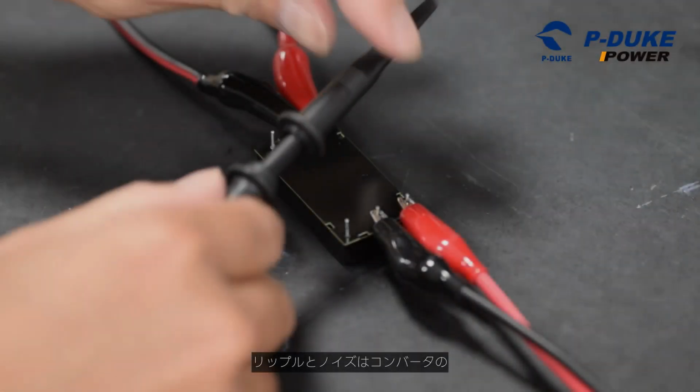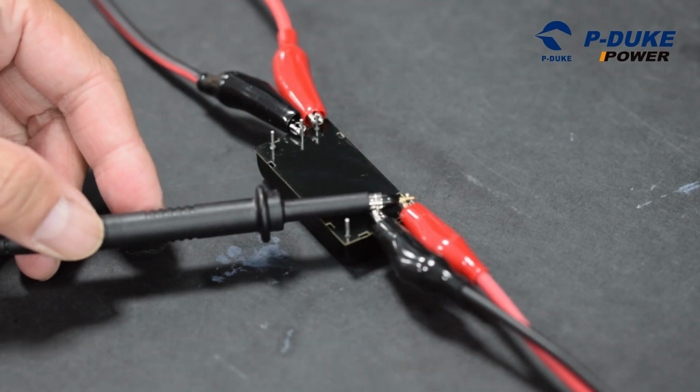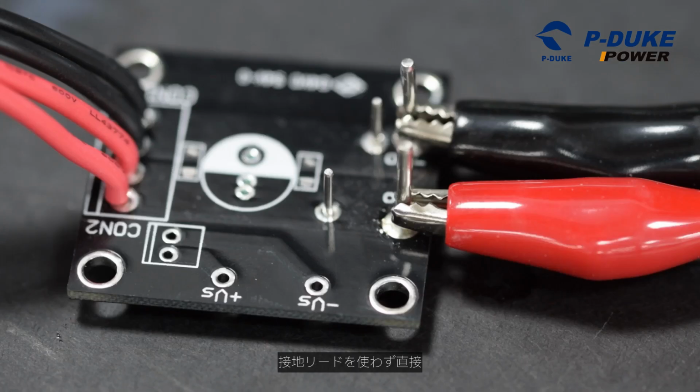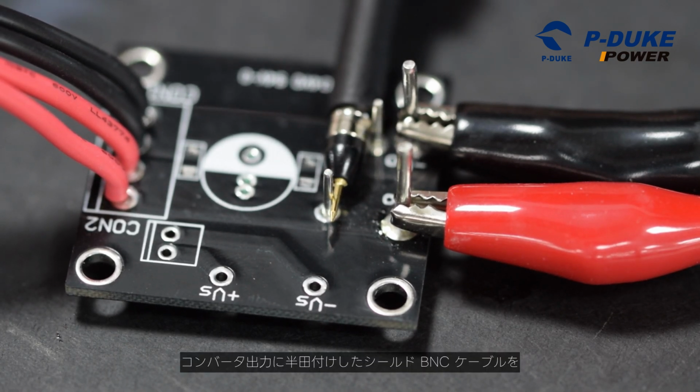Ripple and noise are measured directly at the output of the converter with a bandwidth of 20 MHz. For the correct measurement of output ripple and noise, we recommend connecting the probe directly to the output of the converter without using a ground wire. If this is not possible, you can also use a shielded BNC cable soldered to the output of the converter.